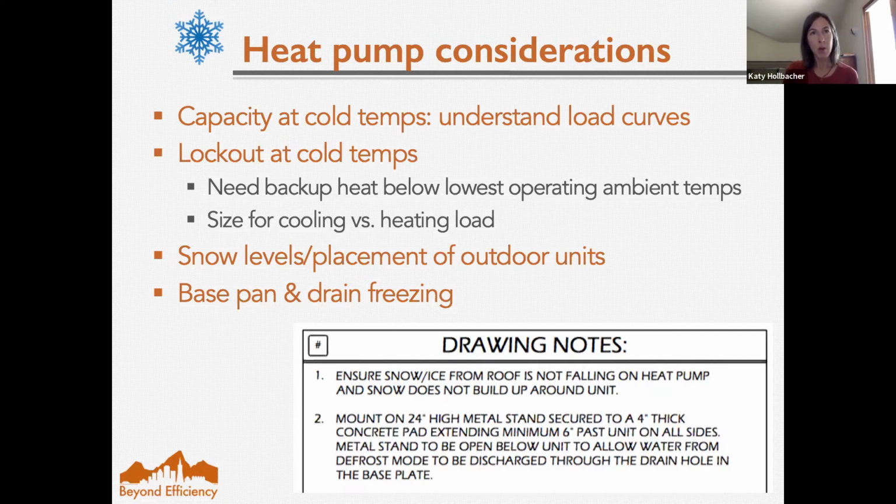And on that note, Kara had me add this as a good point: if you are designing something and you realize that you are going to need backup heat because of the design temperatures and the system you're using, it can make sense to size that heat pump for the cooling load, and you just get what you get out of the heating components since you're going to have that backup anyway. So that can be something to keep in mind.